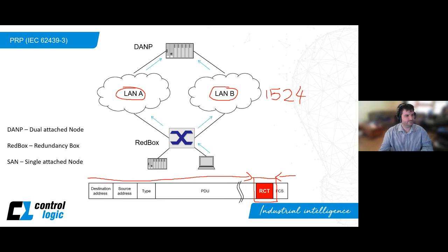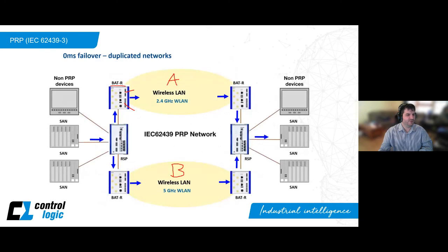Cool. And one more question. What industries do you normally see these protocols being used? The PRP and HSR protocols specifically are mainly being used in the power industry. However, PRP has a lot of niche applications, such as the wireless one we talked about, which is getting use wherever it's suitable. We've worked with some system integrators who have done SIL-based safety systems using PRP.